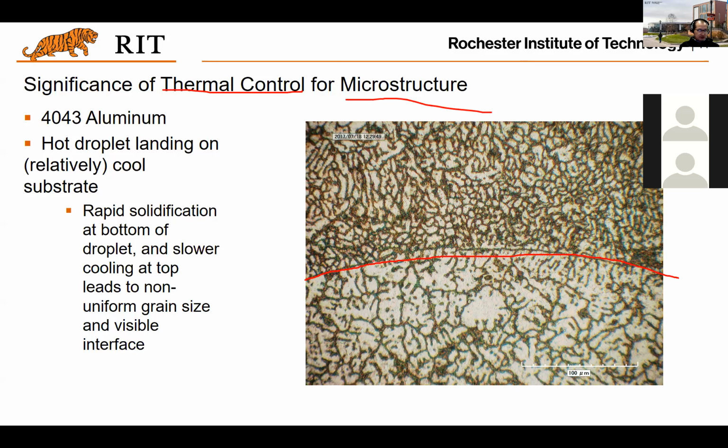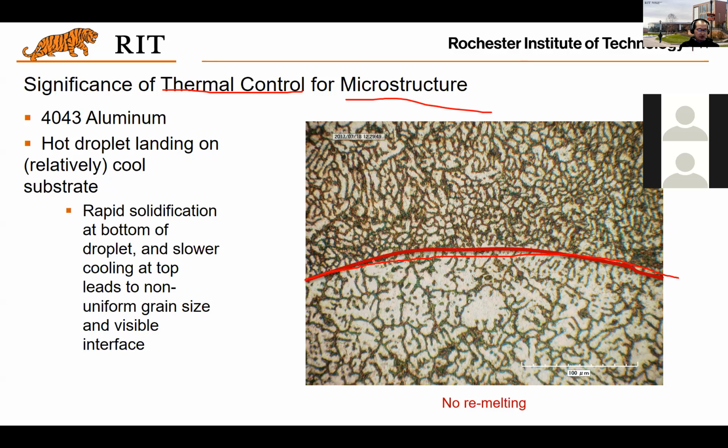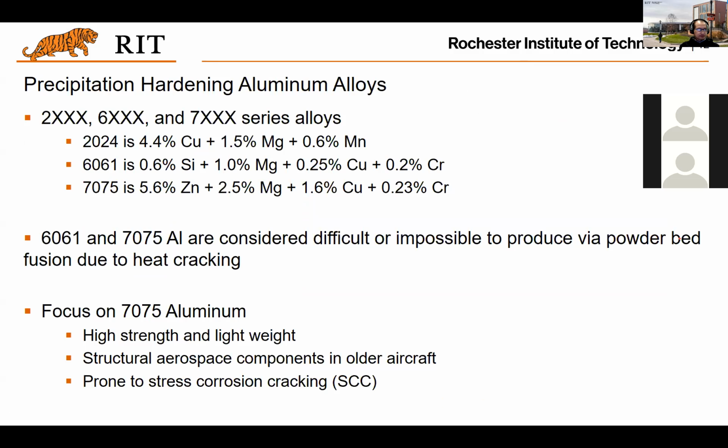So how to overcome this? And that requires a little kind of thermal control, right? Basically, you want to control the temperature during the printing process and make the heat distribution more even, such that such kind of interface will be minimized, and the structure of the metal prints will be better, and the mechanical property of the prints will be much better.